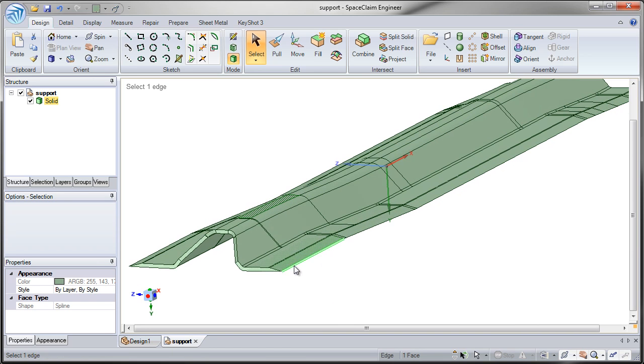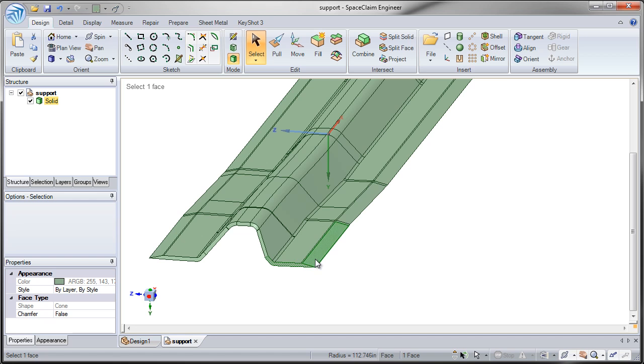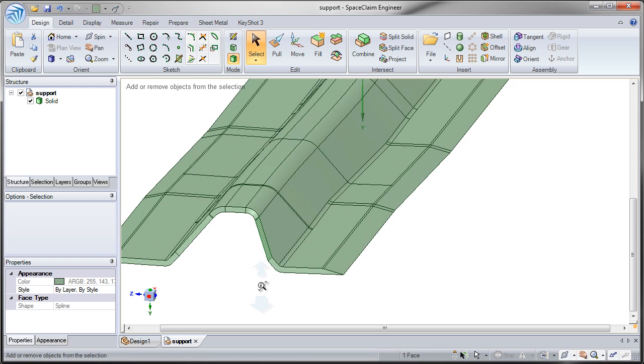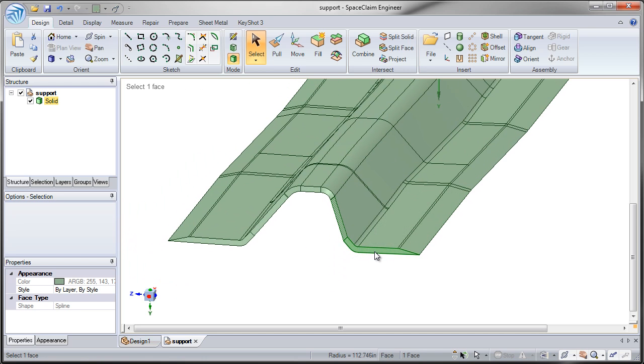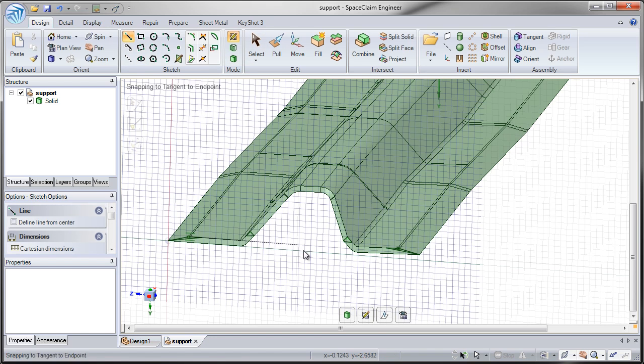So what we'll do to start this is I'm going to select on this front face and start to sketch on it. Now remember, we can select a plane and start to sketch on it. However, if we can't select on a plane to do our sketching, if this is a cone, if this is going to be a spline or different face, I can also simply click 3 points, 1, 2, 3, and define a plane. So I'm going to go to a plan view to start sketching on this.